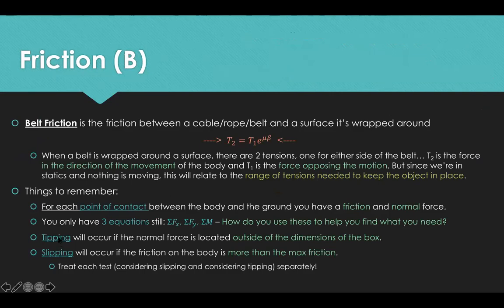The last thing is when you're doing a friction problem, you're solving 2 different conditions. You want to see if the box will tip first or if the box will slip first, which means you're going to end up doing 2 very separate calculations. I can't stress how important it is to understand that they are entirely separate from each other. So the first condition I'm going to talk about is tipping. If I'm pushing on a box, is the force that I'm applying going to cause the box to rotate, like flip over essentially?